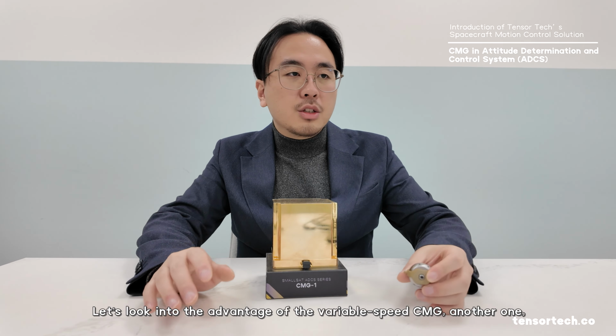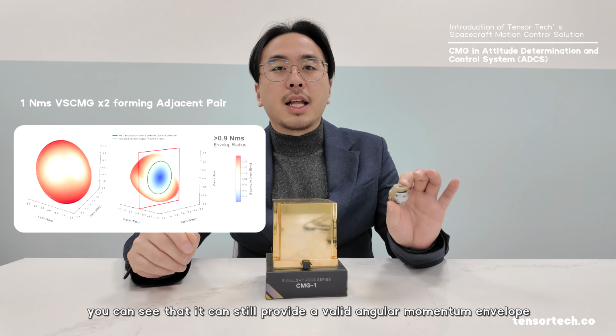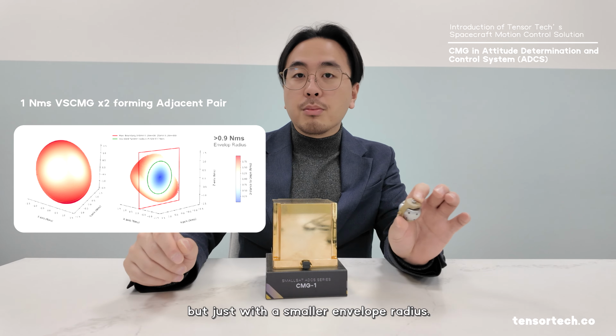Then let's look into another advantage of the variable speed CMG, which is its redundancy capability. When you have 4 CMGs and then 2 of them fail, leaving only 2 variable speed CMGs, you can see that it can still provide a valid angular momentum envelope, but with a smaller envelope radius.